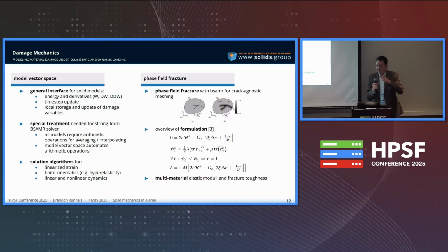Now, a couple of us were talking about this before the session. If you do any kind of solid modeling, you know that really it all comes down to the constitutive model. So that 81 component tensor, that's a pain, right? And that's just the beginning. That's just assuming that you have the best case scenario, just linear elastic. If you're doing plasticity or viscoelasticity or pretty much anything else, all of a sudden you start accumulating all these other variables that you need to track.